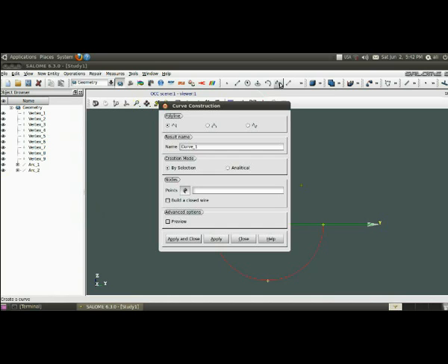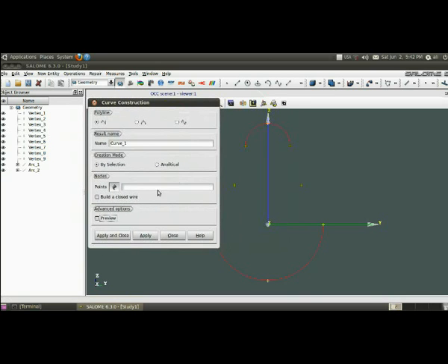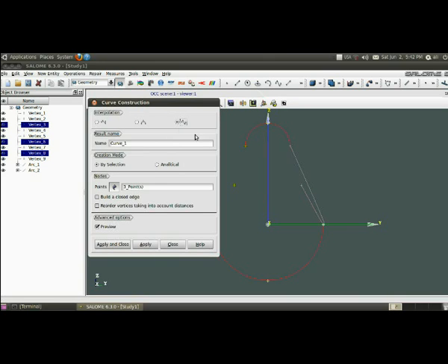Okay, we have to make two curves. To do this work, we have to press the shift button and select our appropriate points, and we can activate the preview command and use the interpolate function, and I select again, and you can see our curve is much smoother than the other one.